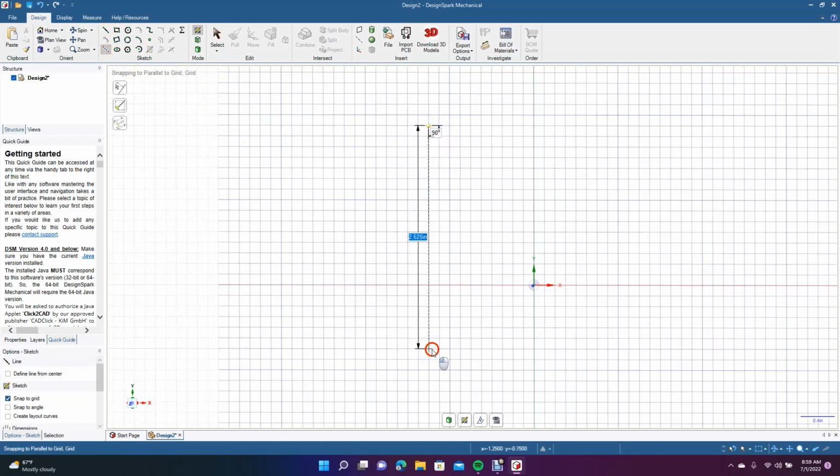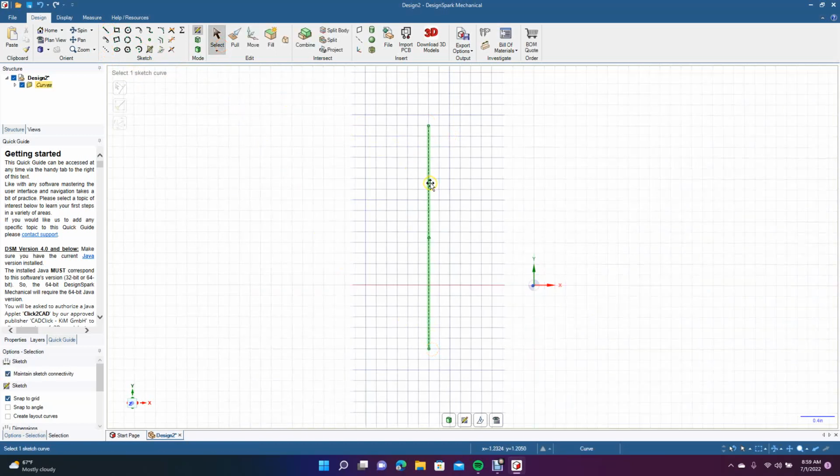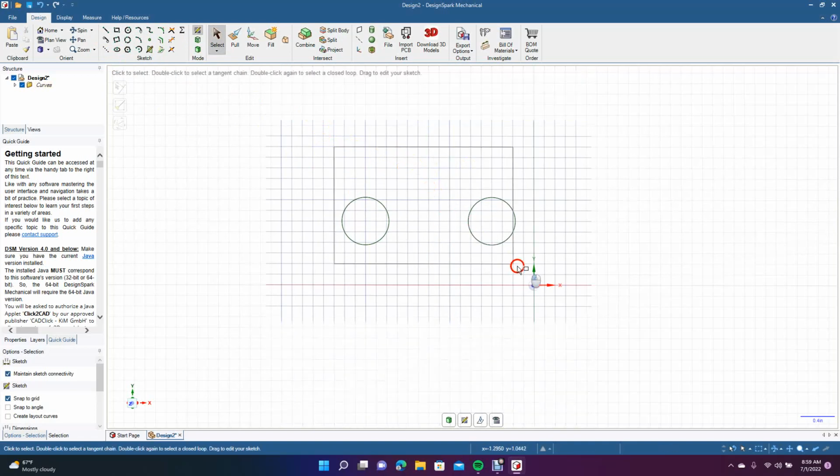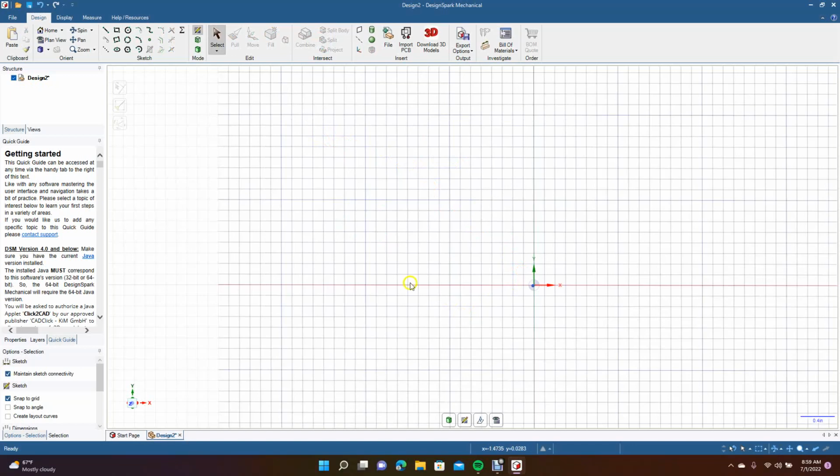Then you can right mouse click on it, set as mirror. So now you can draw one thing over on the left, and it shows up on the right. So that's going to be your construction line. And later on, you can get rid of the lines, that's what's nice about them. You just use them as a construction to help with your drawing, and then move on from there.